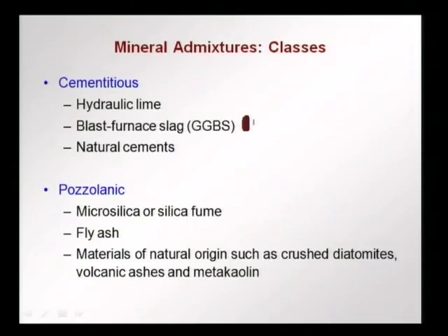Another very important group of mineral admixtures are called pozzolanic admixtures. Examples of these are microsilica or silica fume, fly ash, and they could be materials of natural origin also, like volcanic ashes, which gave the name pozzolanic, coming from the Italian village of Pozzola. And these now are not cementitious, that is, they do not react with water, but they react with the calcium hydroxide. Cementitious admixtures react with water directly. Pozzolanic admixtures react with calcium hydroxide and water to give calcium silicate hydrate.